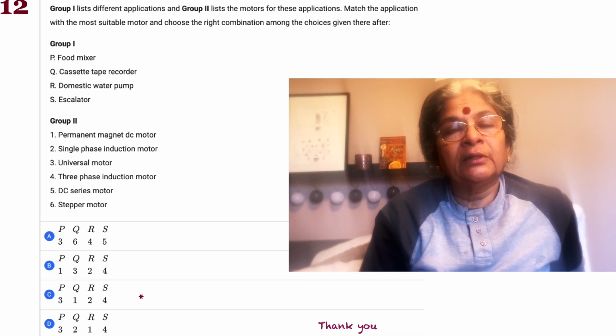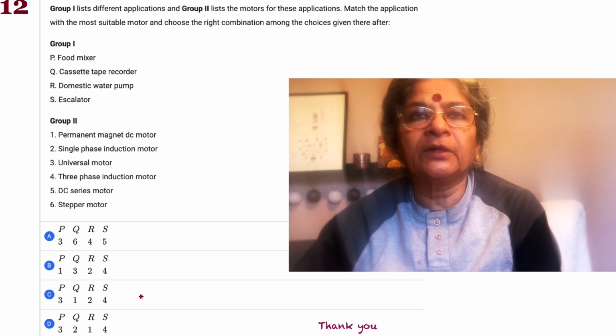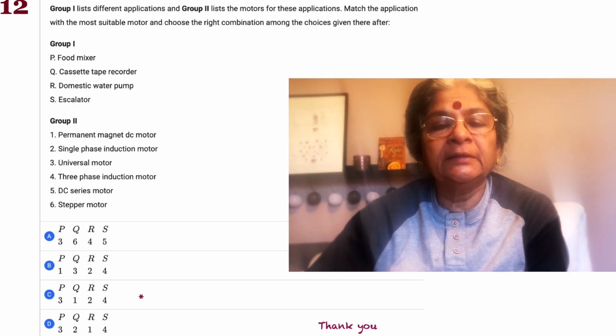That concludes the last of the sessions in the induction machines domain. In this section we were essentially talking about the power scenario in an induction motor. From the power input, the first throwaway happens to be the stator copper loss and stator core loss.